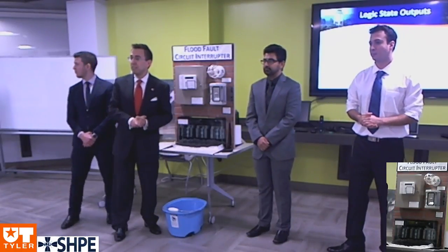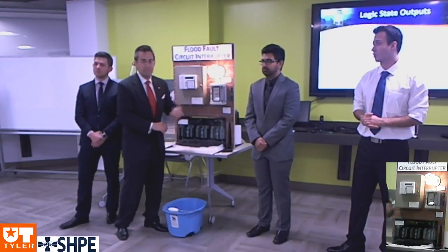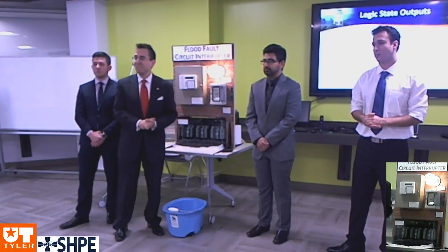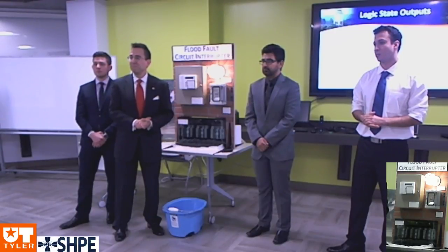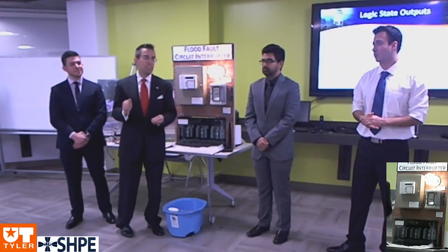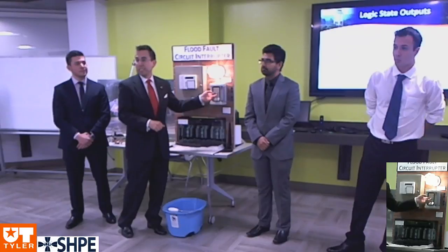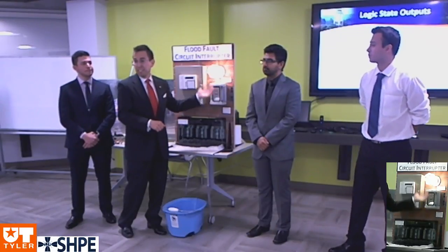So this thing will automatically shut off the power when the flood waters rise. That's good. Will it automatically turn the power back on when the flood waters go down? That's another great question about our shunt trip. The shunt trip we selected is only equipped to turn the system off, so it can take it from on to safety to off.